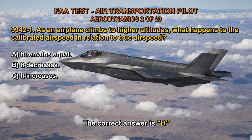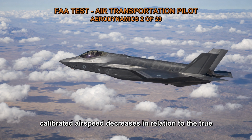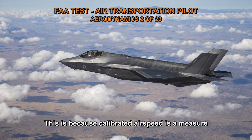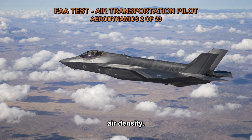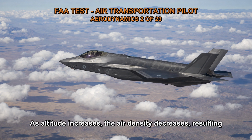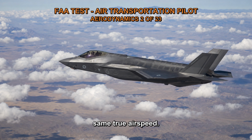The correct answer is B. As an airplane climbs to higher altitudes, the calibrated airspeed decreases in relation to the true airspeed. This is because calibrated airspeed is a measure of the dynamic pressure sensed by the aircraft's airspeed indicator, which is based on the local air density. As altitude increases, the air density decreases, resulting in a lower calibrated airspeed reading for the same true airspeed.